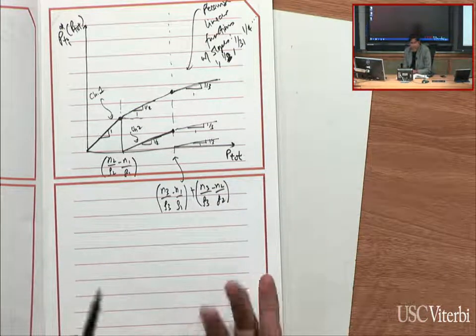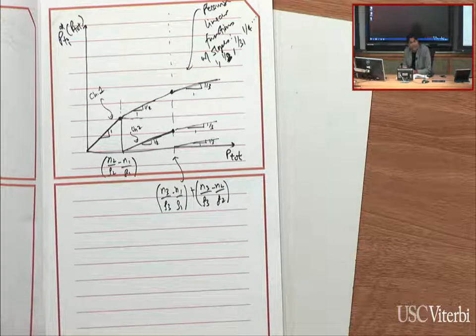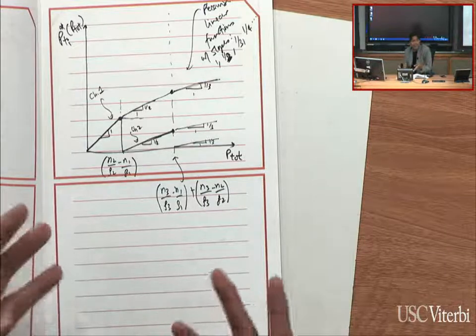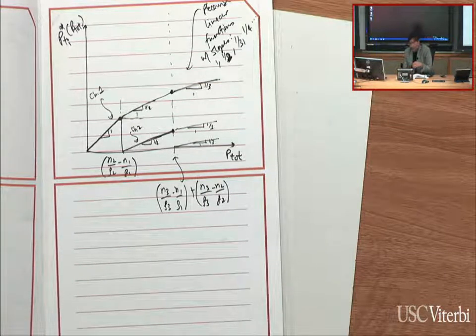And in wireless networks, we use it. Whether it's a single user or multi-user OFDM system, if you care about maximizing the sum rate, water filling is the solution that you use. Years ago, I had a collaboration with Sprint Labs, and they had just started to roll out WiMAX as a protocol, based on OFDM and multi-user OFDM.